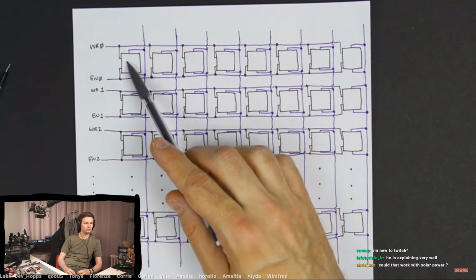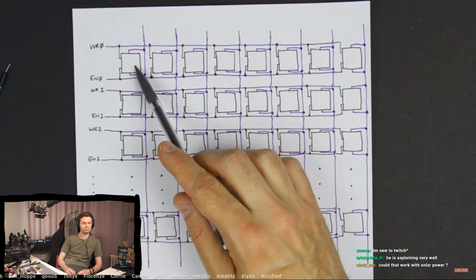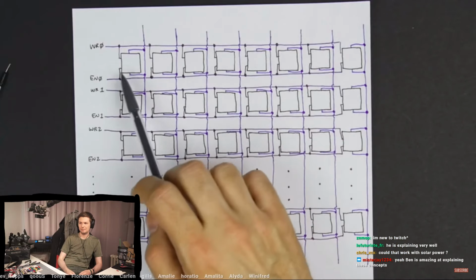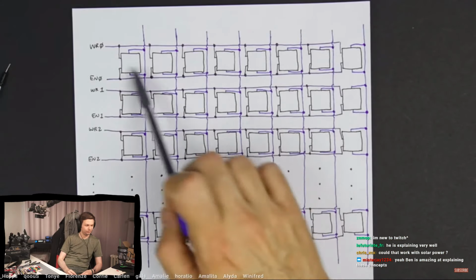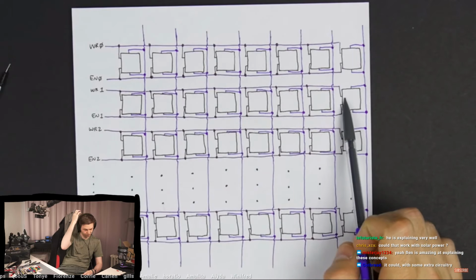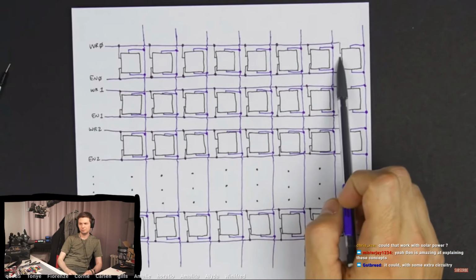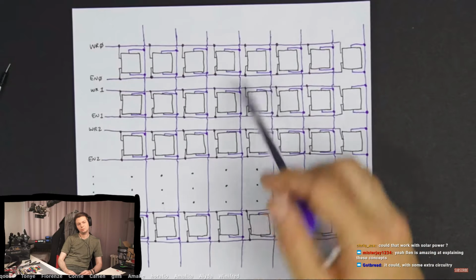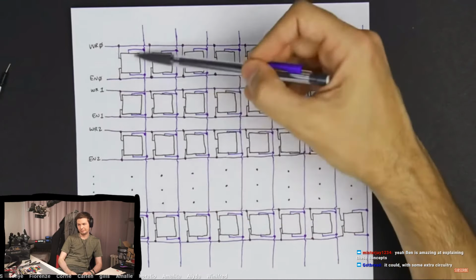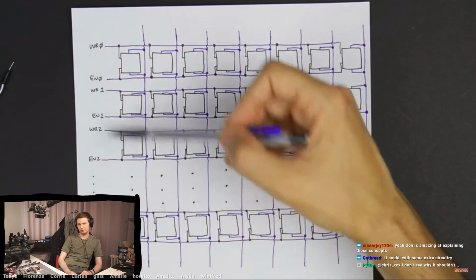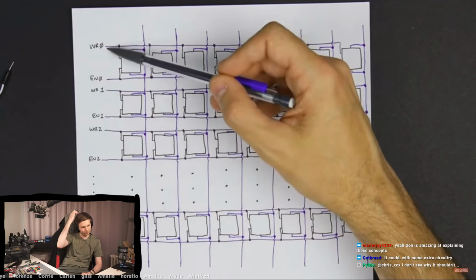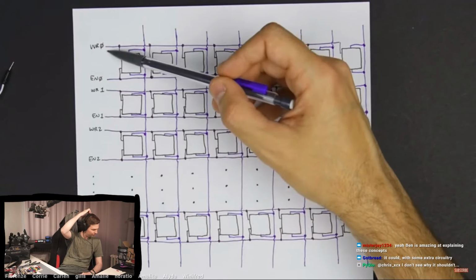We're basically using static RAM just because it's more convenient, because we don't want to have to build that refresh circuit. So for our computer, an easy way to think of it is each of these bytes is essentially just like the registers that we've already built. So you already know how these work. The thing that's a little bit weird now is that we have a separate write signal for each of our 16 bytes of memory, and we have a separate enable signal for each of our 16 bytes of memory. And so that could get a little bit unwieldy.